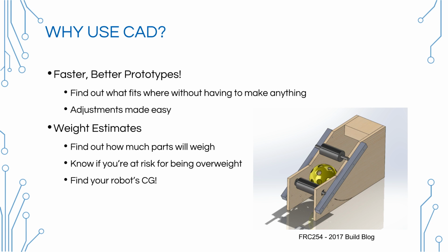But either way, you can sum up all of your custom parts that you've designed, all of the metal that you're going to cut, the wood, the plastic, etc., and come out with a final weight that you think the robot's going to weigh. And so not only does that tell you if you're underweight, but then as you're building the robot, if you start weighing it and it's like, whoa, this is way heavier than we thought it was going to be, you've got something to check back to and figure out if you did something wrong, or adjust at that point as opposed to Swiss cheesing it at the very end because you missed something.